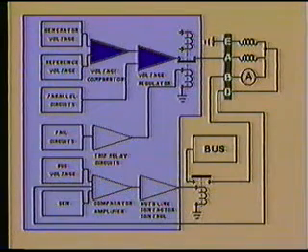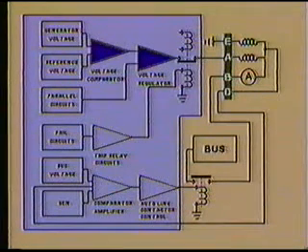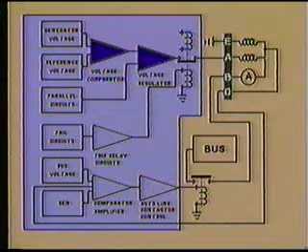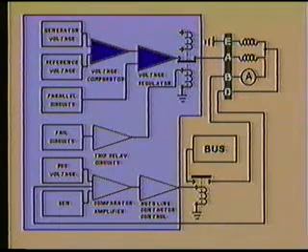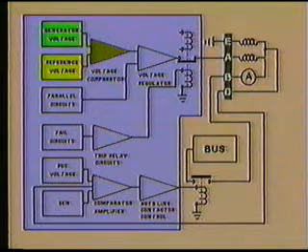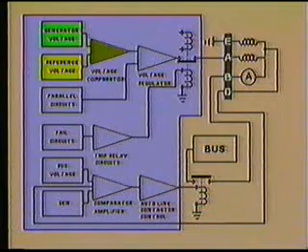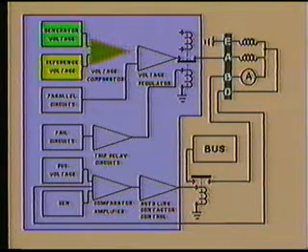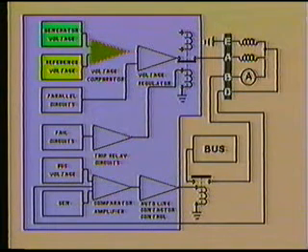After protecting the generator and aircraft circuits, the second primary responsibility of the generator control panel is to regulate the output of the generator itself. This is accomplished by two circuits within the control panel. The first is a voltage comparator that compares the output of the generator with a master reference voltage. When the generator output is less than the reference voltage, the comparator will have an output that will eventually cause the generator output voltage to increase.